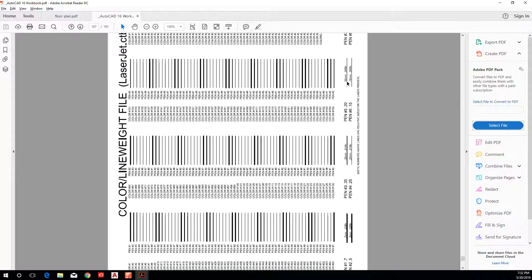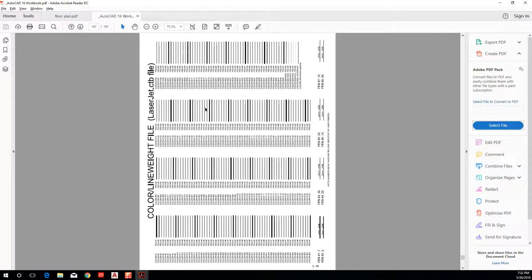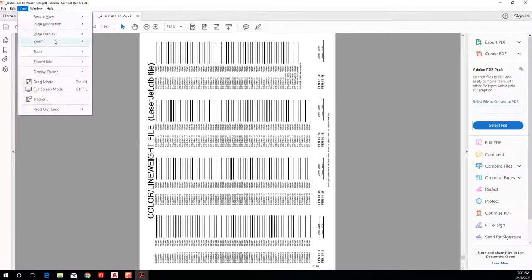And again, Jeff wrote these assignments, so I blame it on him. He kind of is sending you on a wild goose chase, but the idea is that you're connecting that you have a color in AutoCAD, and that color is a line weight, and that line weight has a thickness, and that thickness then correlates to a number, which the number coordinates to a color, right? So somebody could say use pen number 1, or use pen that is 0.2 millimeters, or red, and you would know that all 3 of those things are exactly the same, right? So it connects those ideas. While it's super annoying, I feel like it's kind of genius at the same time, right? Which a lot of his assignments do.